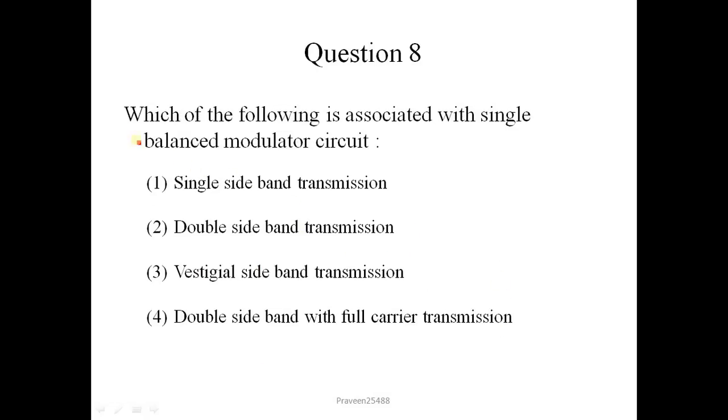Now question number 8. Which of the following is associated with single balanced modulator circuit? In this diagram you can see that the single balanced modulator or mixer is used to generate double sideband suppressed carrier signal. So its correct answer is this 2, double sideband transmission.